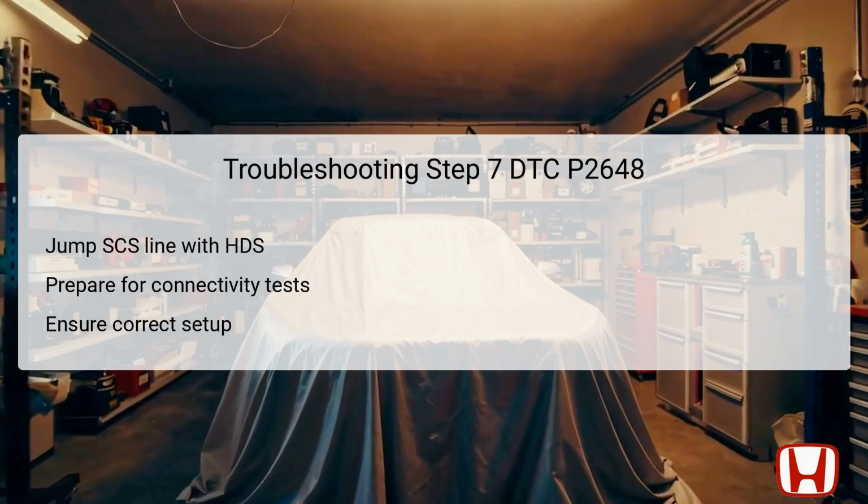The seventh step involves jumping the SCS line using the Honda Diagnostic System, which is essential for bypassing the vehicle's safety protocols temporarily. This action allows technicians to conduct specific tests without interference from existing codes or systems that may inhibit diagnostic procedures. Before proceeding, it is critical that the HDS is correctly configured and connected to the vehicle to ensure accurate data readings and functional tests.